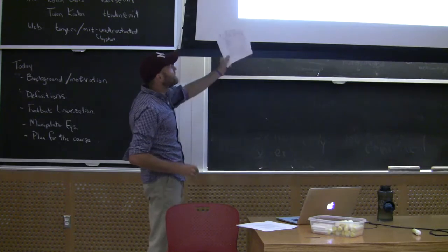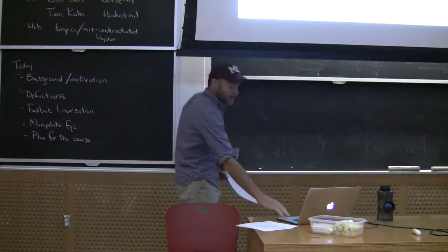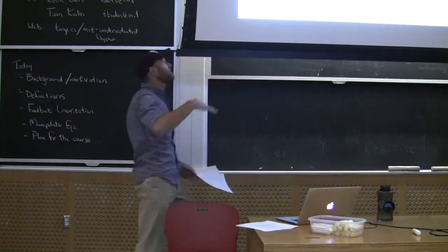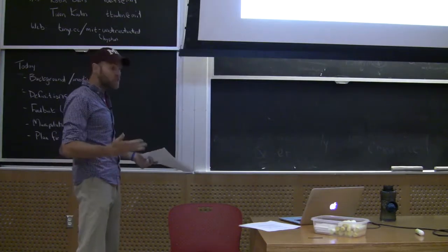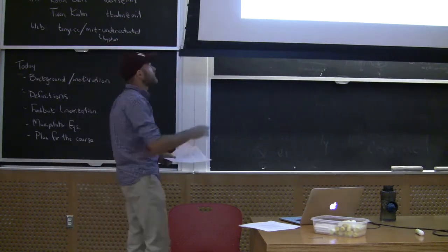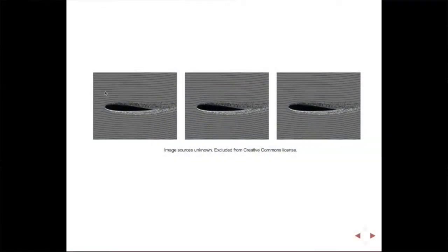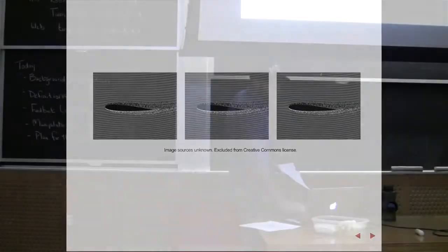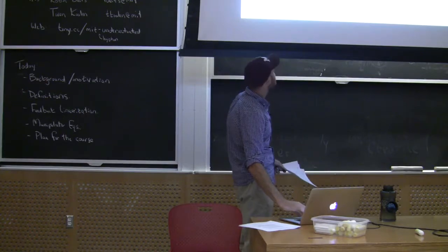So the reason that we do this in the control is because when your aircraft is at a low angle of attack relative to the flow, then we have good piecewise linear models of the aerodynamics. Okay, so this is a wing with these lines being the streamlines. And when the aircraft is in line with the direction it's moving, then the air moves nicely around the wing. If I bring my angle up to a small angle of attack, again, it stays connected to the wing.